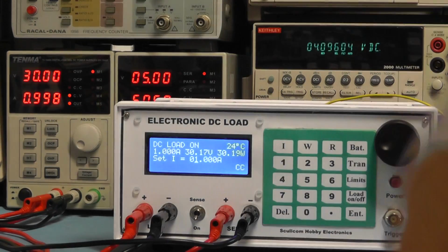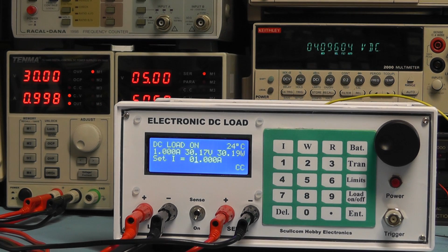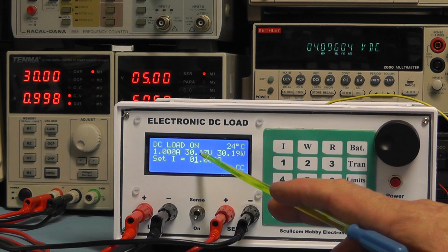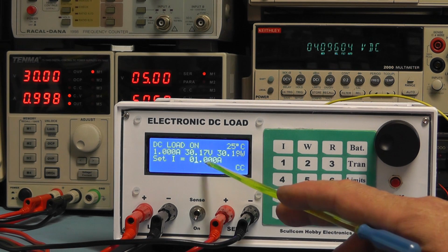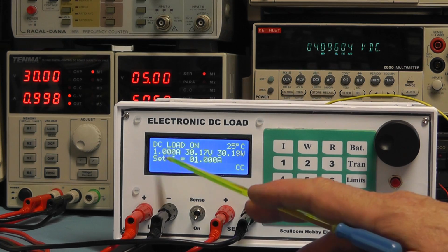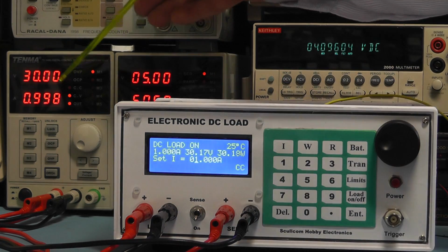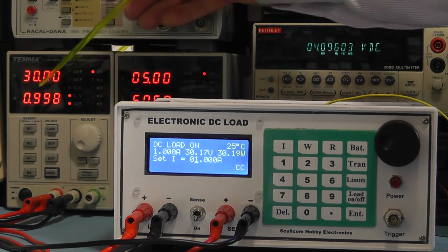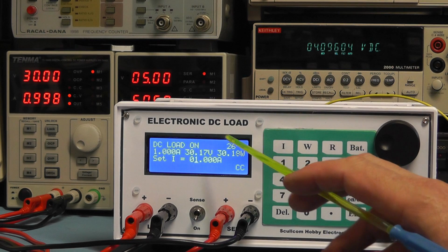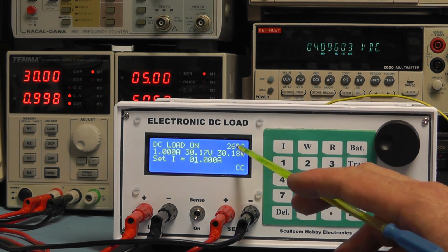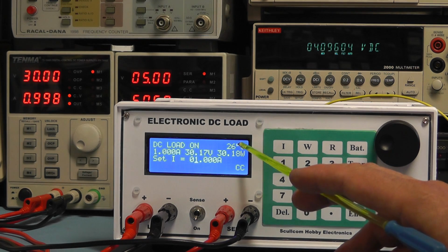So we've got 30 volts there now, and you can see there on the DC load it's registering as 30.17 volt. We've got the current set to 1 amp, the load is on, and we're drawing 1 amp, and it's showing 0.998 amps there on the power supply. So if you leave it like that until the temperature goes up, what we want to do is allow the temperature to rise so the MOSFETs are just warming up, and then go through the final calibration again for